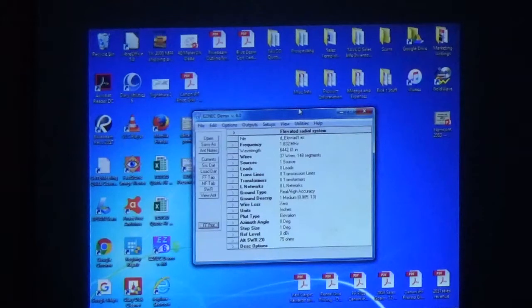I was doing some research on direct fed Yagis, 50 ohm Yagis. That seems to be the big thing. Nobody's using gamma matches or anything anymore. I shouldn't say nobody, but most people don't. They're all direct feed. You get less gain and less front to back, but the overall gain is better. Tom has a whole bunch of defined Yagis, 3 element, 4 element, 5 element, 6 element for 20 meters, then he goes to 17, 12 and all that. You punch in these numbers exactly like that into EZNEC and it comes out right on the money. Direct feed, 50 ohms, wide SWR bandwidth. It's pretty cool. That's how they got there. They use this as the analyzing.